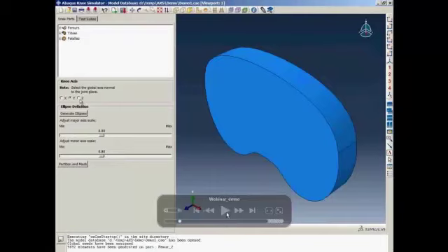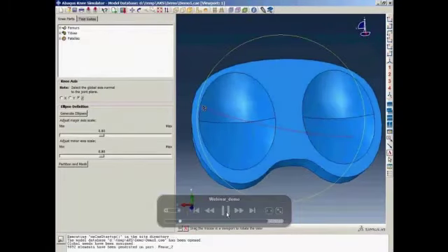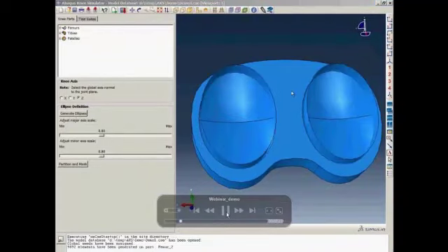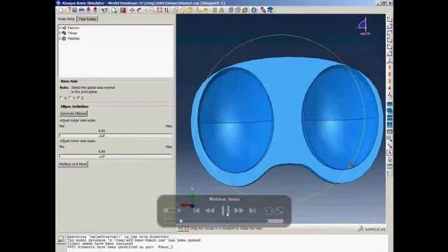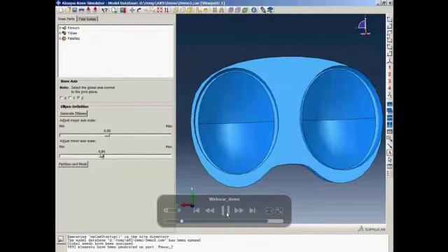So here, this is the semi-automated tool we provide to generate the hexahedral mesh for the contact area. The first thing you'll be prompted for is the axis that represents the global knee axis, which in this case should be the z-axis. This will be the axis we use to generate the ellipses used for the positioning. Now you can see the ellipses are generated, and we provide the tools to control the minor and major axes of these ellipses.